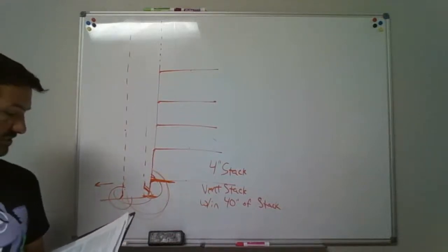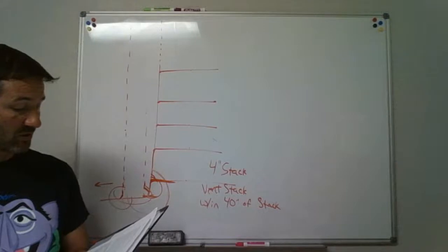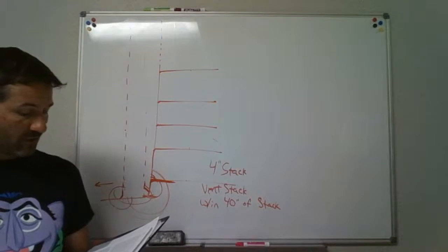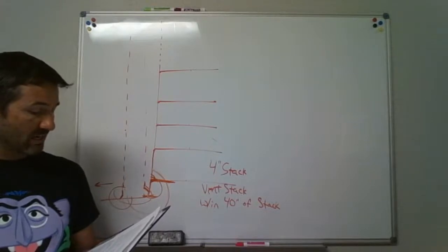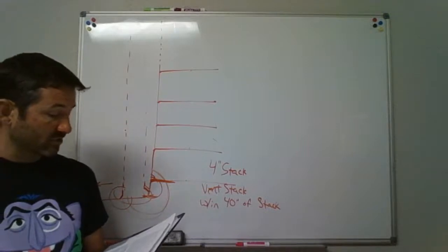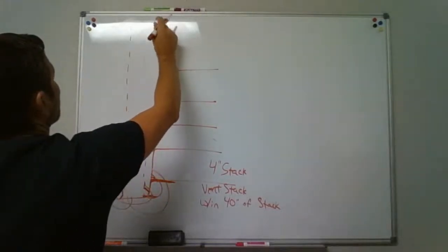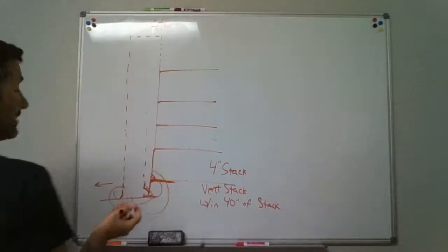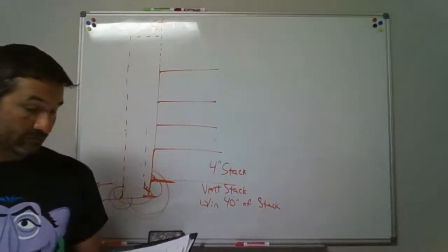Vent headers. Stack vents and vent stacks connected into a common vent header at the top of the stacks and extended to the open air at one point should be sized in accordance with the requirements of 906.1. The number of fixture units shall be the sum of all fixture units on all stacks connected thereto, and the developed length shall be the longest vent length from the intersection at the base of the most distant stack to the vent terminal in the open air as a direct extension of one stack. So it's saying you could take one of these out to the open air. Well, this one can connect back to it. You can connect the two and take one out, that is acceptable.